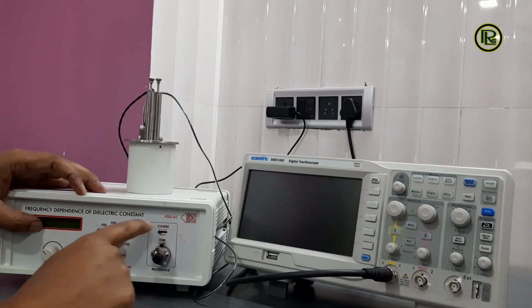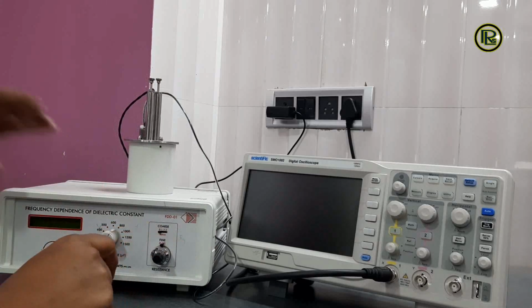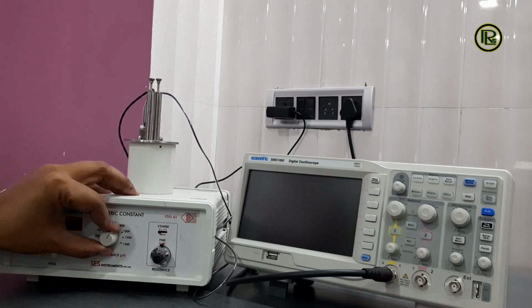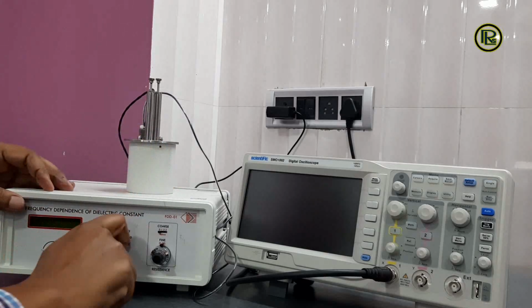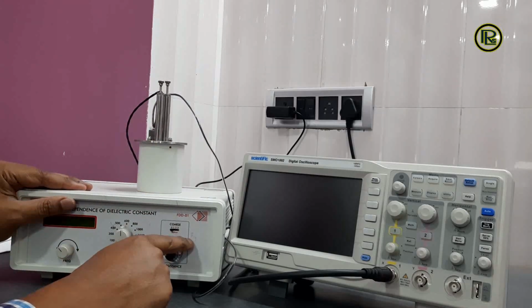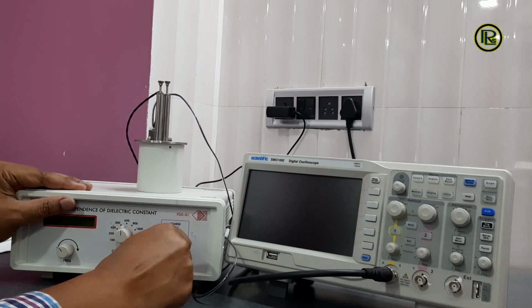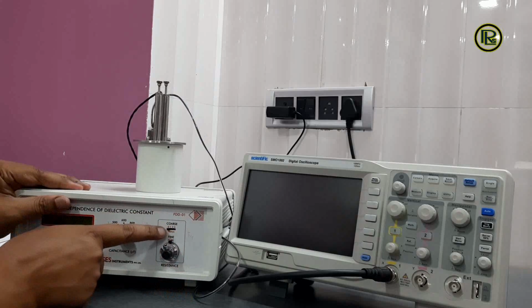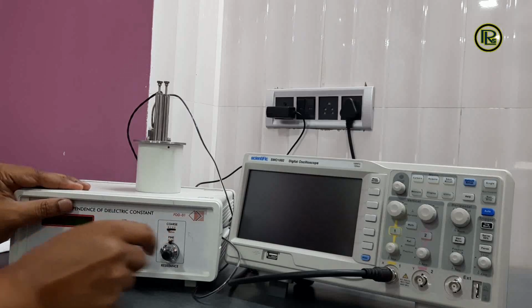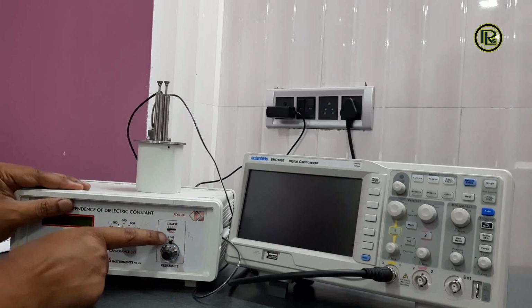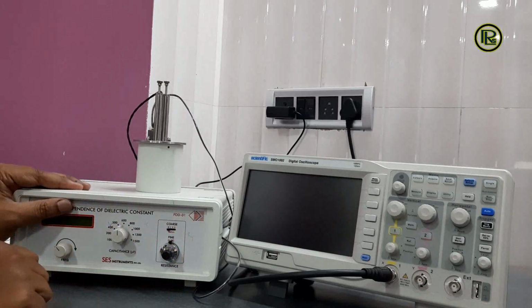And the C4 and the R4 of the fourth arm of the circuit I showed you: this C4 can be varied with this port, and this is in the scale of picofarad, and the resistance R4 can be varied with this port. So it has coarse and fine adjustment. Coarse adjustment can be from 0, 1, 2, 3 up to 3 kilo ohm, and the fine port can be adjusted with this, and this has a range from 0 to 1 k, and there is a small display.